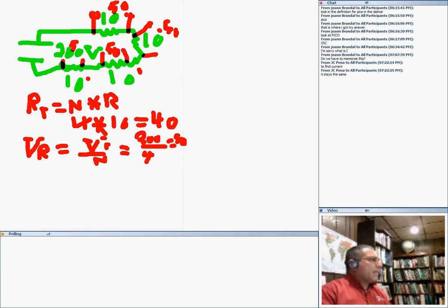They will probably catch you guys in the exam, the German exam. They give you equal resistors, and you start doing all this analysis that Chad showed you. And in reality, you don't have to do anything. What you have to do is just divide the voltage by the number of resistors. Very interesting rule. If all resistors are the same, all you have to do is divide the voltage by the number of resistors to find the voltage across each resistor.